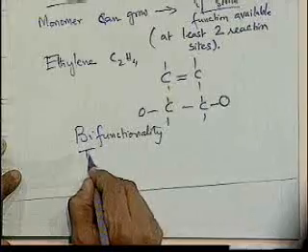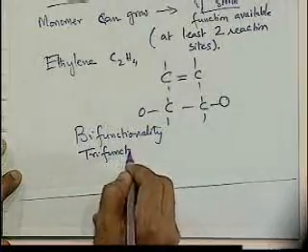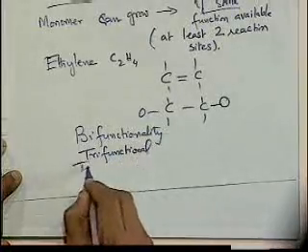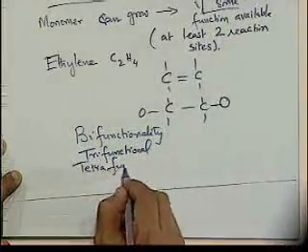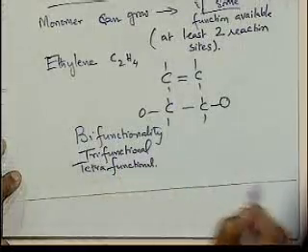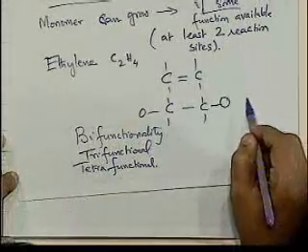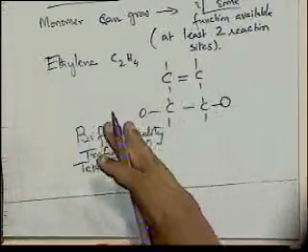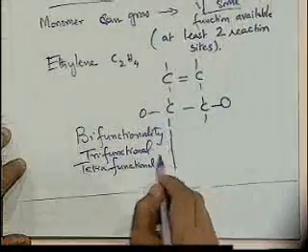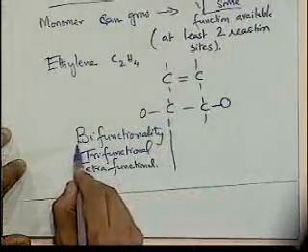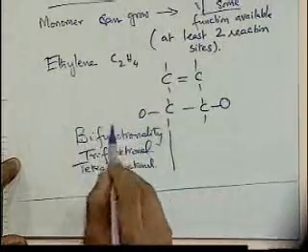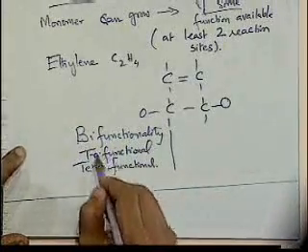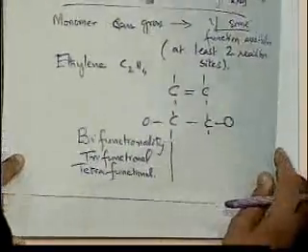There are monomers which have got three reaction sites, and then we'll call them trifunctional. If they have four, they are called tetrafunctional. More than four creates problems because of space constraints. It's not possible for the monomer to grow. And so typically, for a monomer to grow into a polymer, you need at least one double bond, that is a bifunctional monomer, or you may have trifunctional or tetrafunctional monomers.